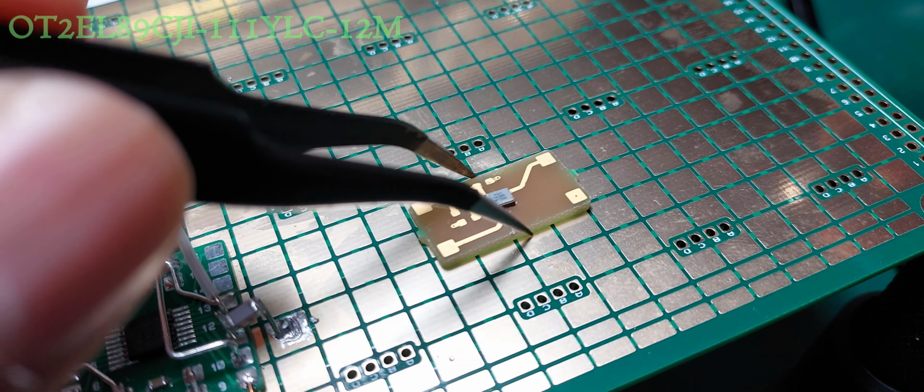The next task was to deal with the quadratic in the room. Directly compensating for on-resistance mismatch, although possible, is inelegant and messy. Luckily, the solution is already known to us from the Delta Sigma video. The damp switch patent describes a curious op-amp circuit which some may know as a negative resistance synthesizer. Instead of consuming current, it pushes a current into a voltage source proportional to its voltage. In other words, it can buffer the output of an analog switch without being directly in series with it.